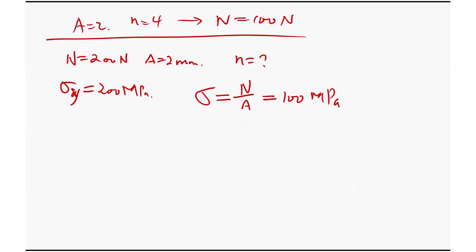Remember before, when we hang 100 Newton, what's the stress? Think this way. Last time it was 50. So when you hang 100, the stress is 50. Now I have 200, double, so you should get double. You think this way, you don't need a calculator. So you get the stress of 100 megapascal. Sometimes maybe verbally I said pound wrong, but it's Newton.